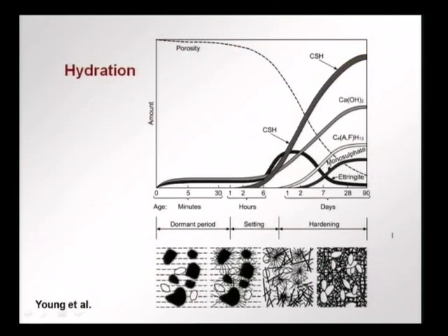Now, these reactions occur over a period of time. They do not always occur at the same time, and each of them has a different rate of reactions. Initially, as soon as we mix cement and water, in a few minutes we have the ettringite formation occurring. In this curve, you see that ettringite has started to occur along with some calcium hydroxide. In a few hours we have setting occurring, we have the ettringite almost completing its hydration. Later on the ettringite changes into monosulfate.